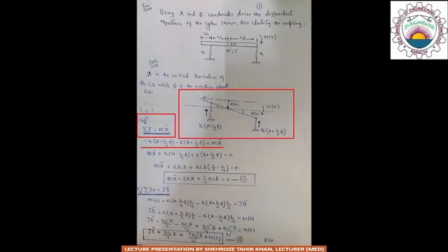In this equation it should be noted that we take out k as a common factor, where kx is the spring force produced by the stiffness elements k, and k into L by 4 theta comes from the relation S is equal to R theta, due to the fact that when the rigid bar tends to rotate about its CG, it will produce an arc length which is equal to S is equal to R theta,